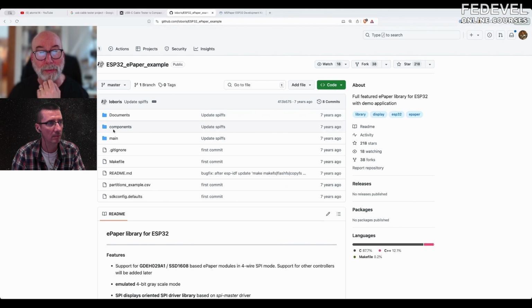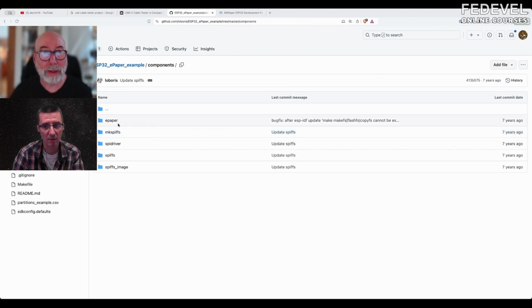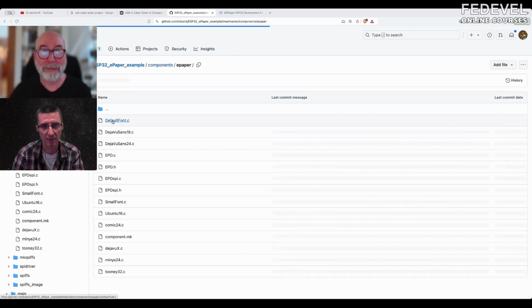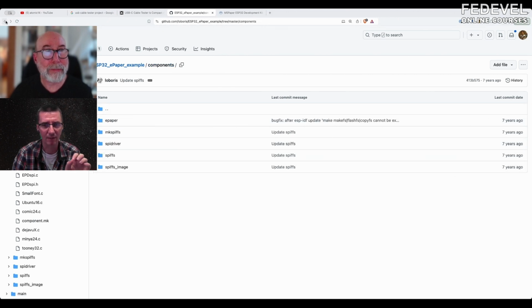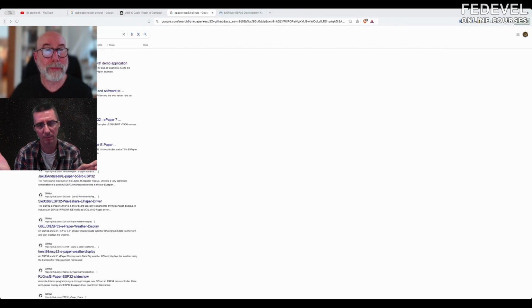I think one of the big problems is that reverse engineering the waveforms for actually driving the boards is quite complicated. Yeah, that's what I had problems with. I ended up trying to find the data sheets of the controller, because there are many registers, and any small changes influence how durable the picture was, or how black it was.